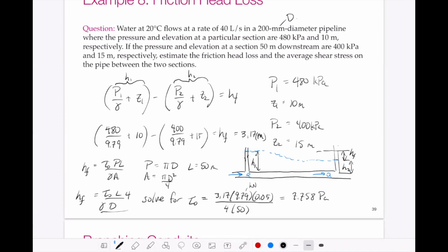So if we were to open that up through a pressure tap, instead of a pipe going straight vertically, if we followed a line up there at the very top, the pressure is the atmospheric pressure. So the total distance that would travel up would be our pressure head. So this is what they mean by hydraulic grade line or pressure heads.